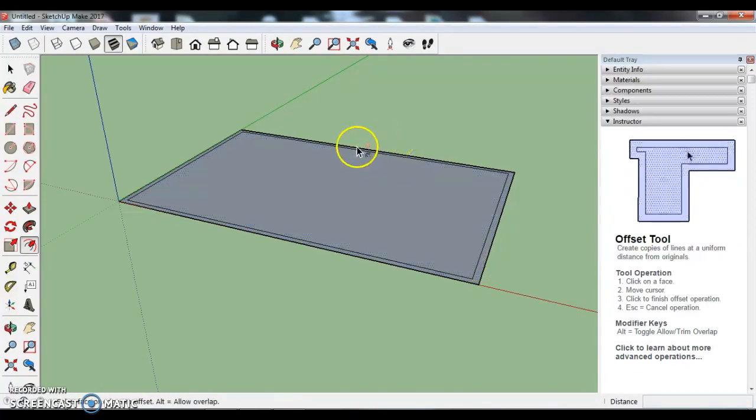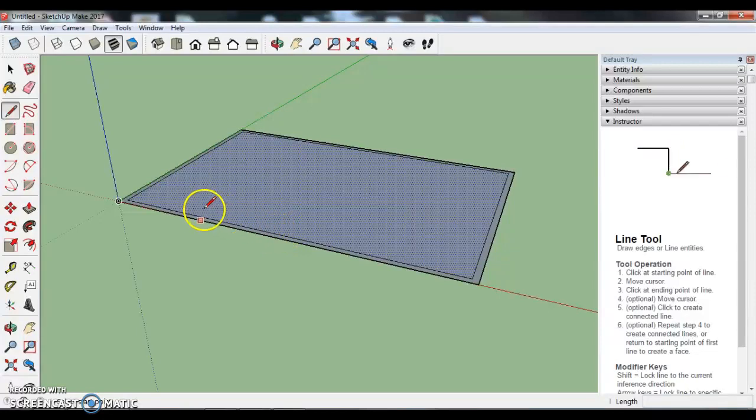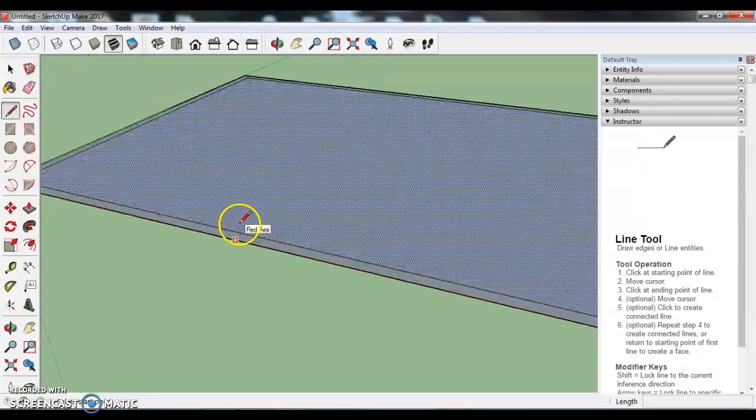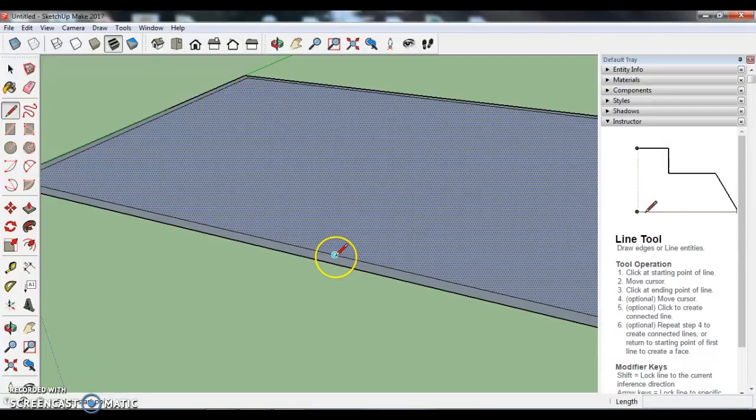Now, I also want to make a wall somewhere on the inside here, and it's not too important where right now, but I want to make an interior wall, and to do that, I'm going to use the line tool. It's located over here, or as you might guess, it's the letter L on the keyboard. And notice as I zoom along this interior rectangle, I'm trying to stay on the interior, I'll zoom in a little bit more. It snaps to that rectangle, but it also snaps somewhere else to the midpoint. That's just something interesting to keep in mind.